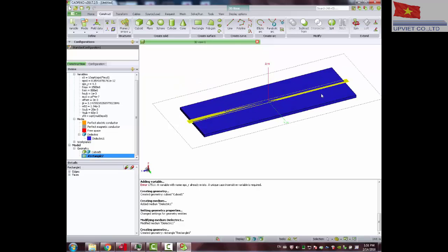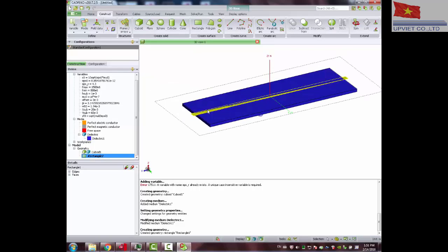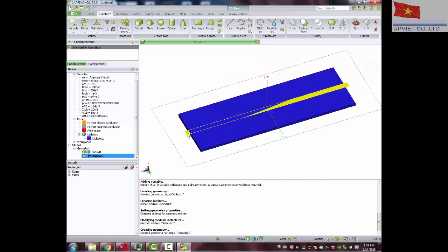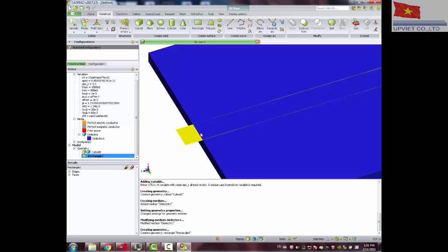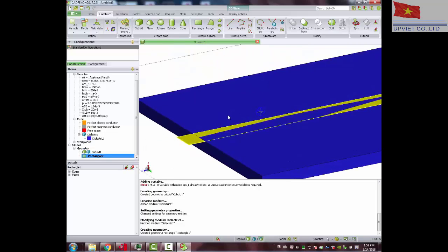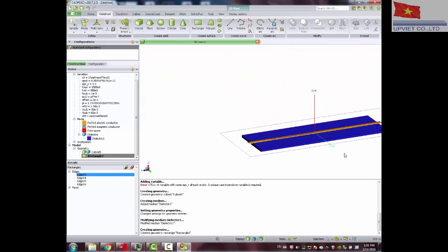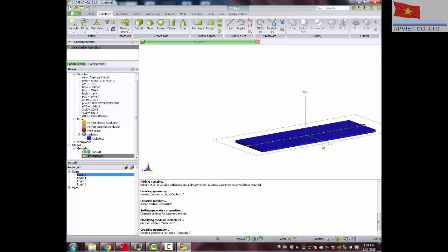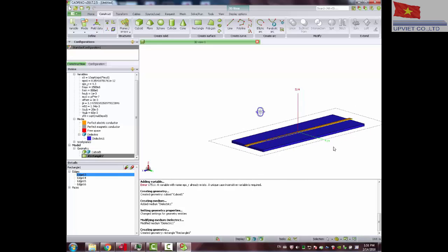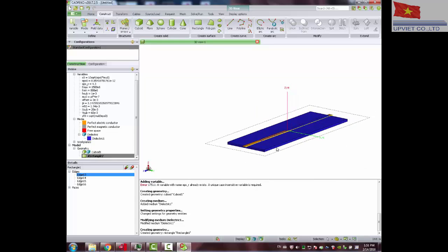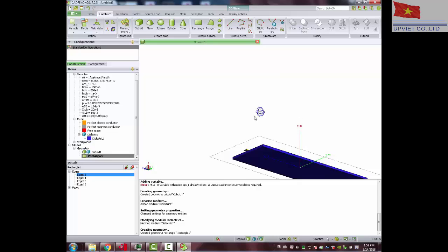You can see here that the microstrip line is longer than the substrate, which seems to be a little bit odd. The problem here is we need to do this way because we are working with a finite substrate. In FEKO, you have the option to operate with an infinite substrate, but in this case we are going to make it finite. The simulation is more complex, but it pays off because we have better results if we are going to compare with measurements and